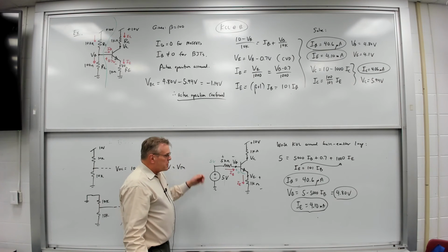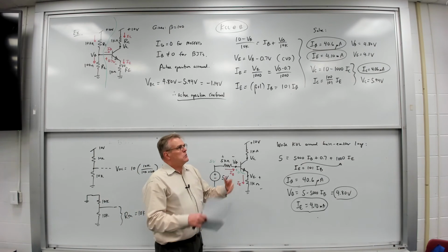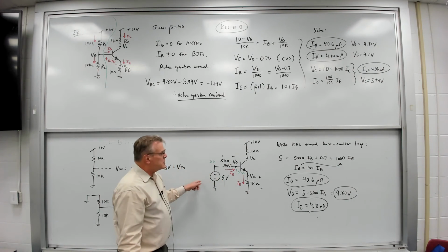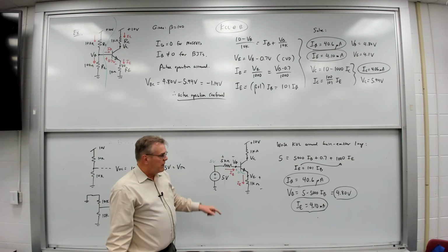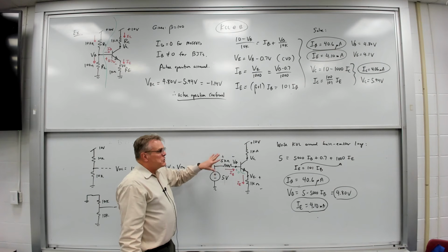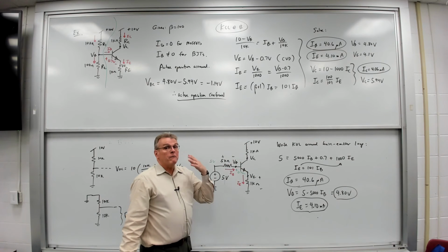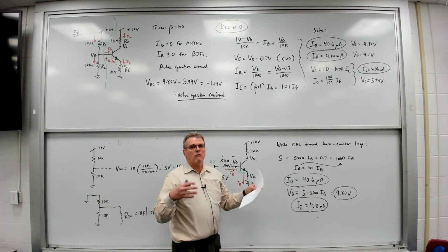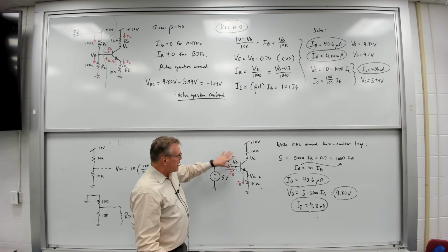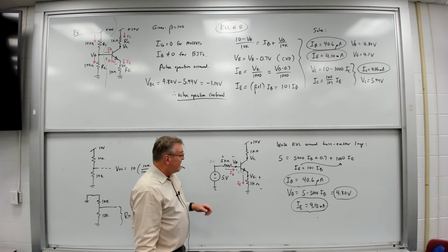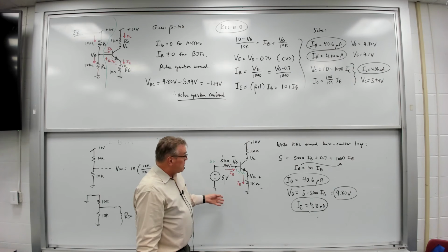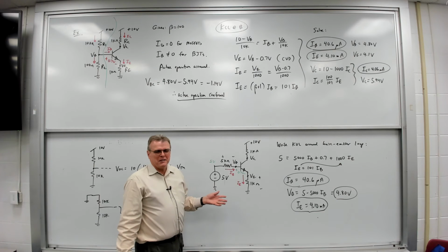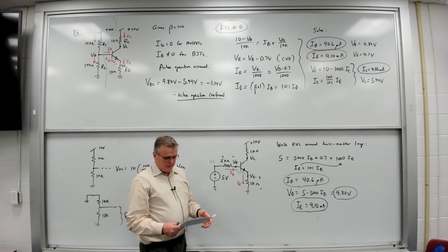So doing it this way is not really necessary in the modern era. If you want to solve simultaneous equations, you have programs like Mathematica to do that for you. What it does help you to do is to visualize how to solve the problem. Do the base emitter loop first, solve and get those answers, and then what else you need to do will become very clear to you. It helps you from getting lost in all of the equations if you just try to blindly start writing equations down. Before the modern era of computers, this may have saved you some time and made some calculations easier. Nowadays, that's not so necessary, but it still is a good visualization aid.